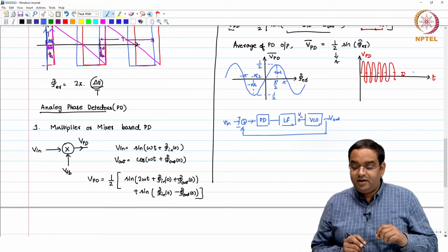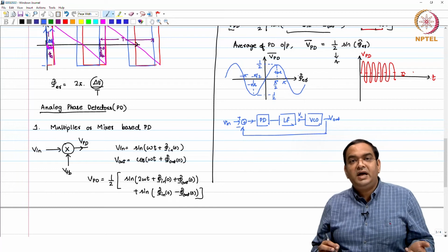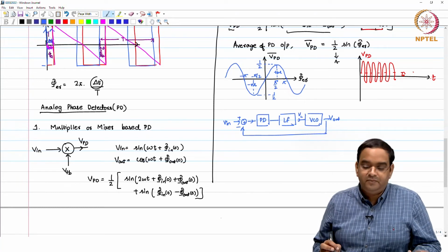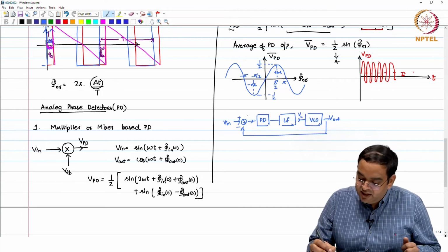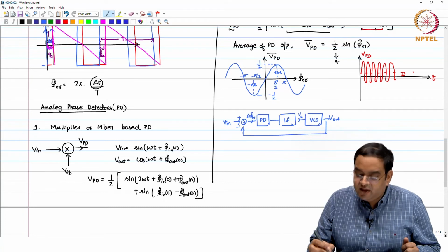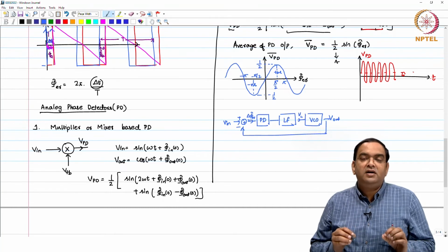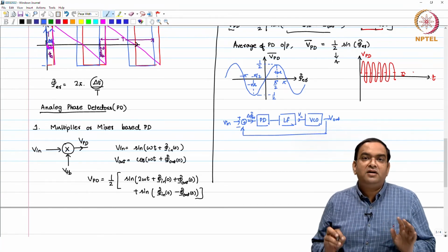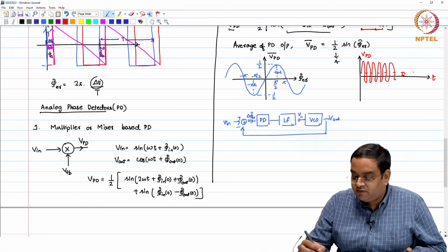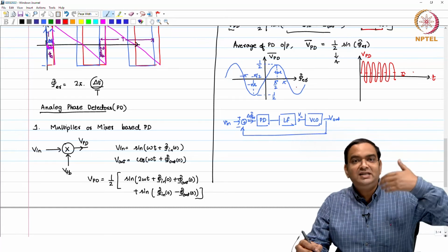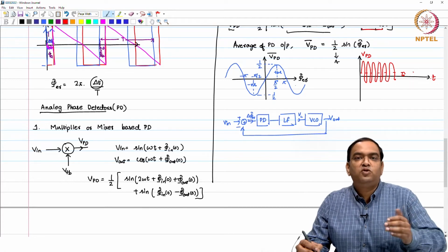But here it actually depends on whether the phase error is greater than pi or within 0 to pi. If there is a small phase error here, it is not going to be processed in a linear fashion by our phase error detector. Even if the phase error is greater than pi, you see the loop sign changes completely, which will not make the PLL go towards lock.